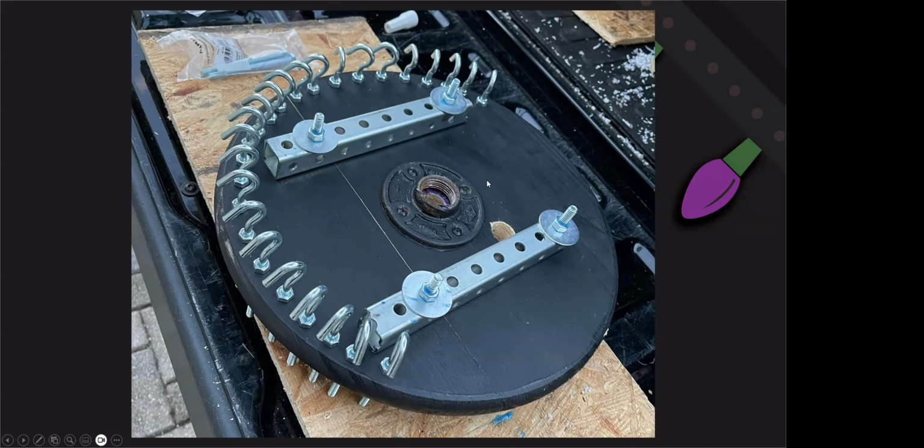But if you're going to make this work, do some type of reinforcement around here in both directions. The wood is going to typically break along the grain, so you want your reinforcement in that direction. Look to see where that grain is when you're putting these on here so that you're not putting all your weight on one side and the other, forcing it to bend in that direction and break there.